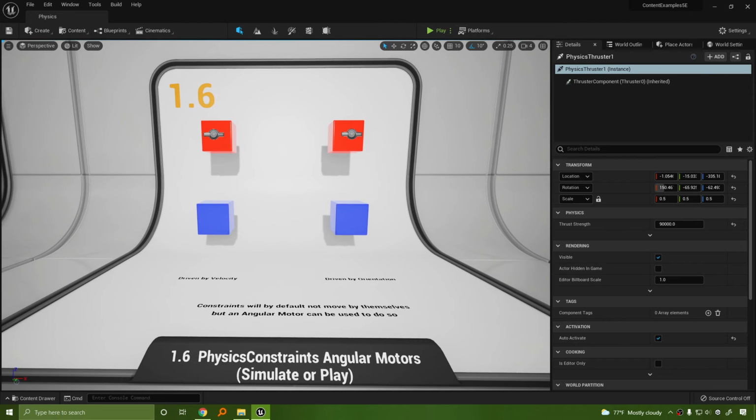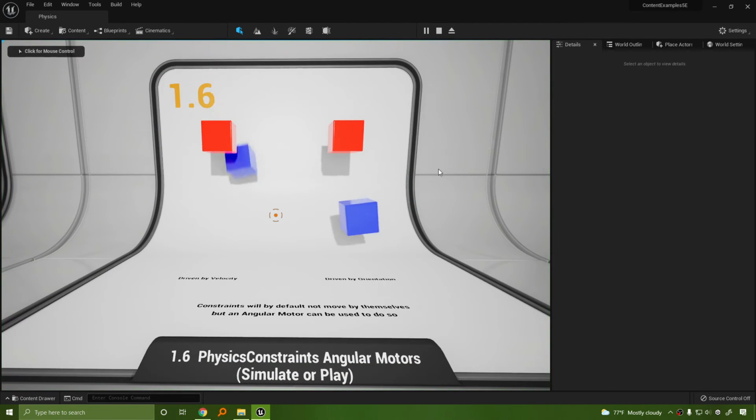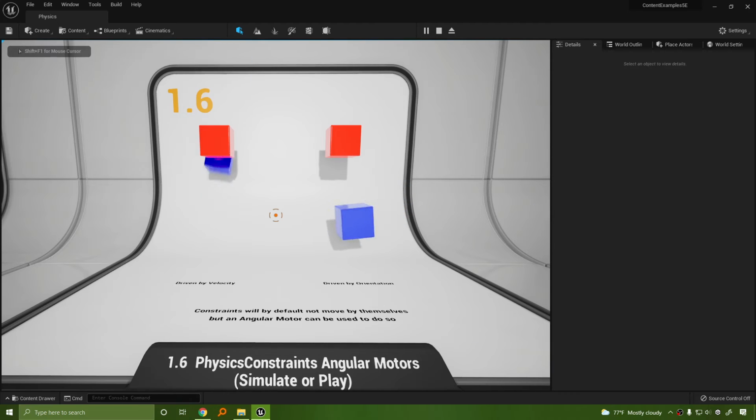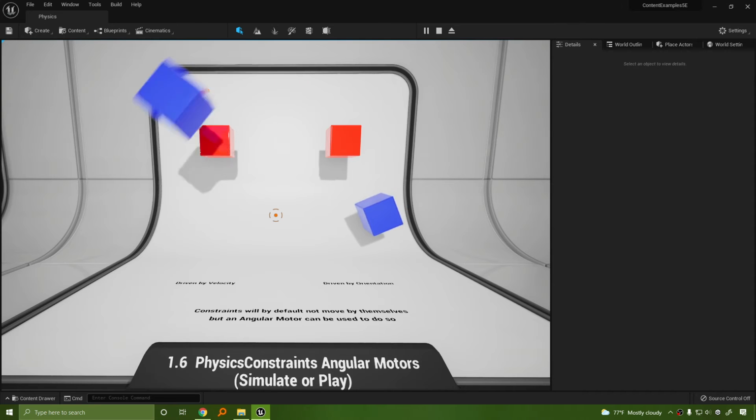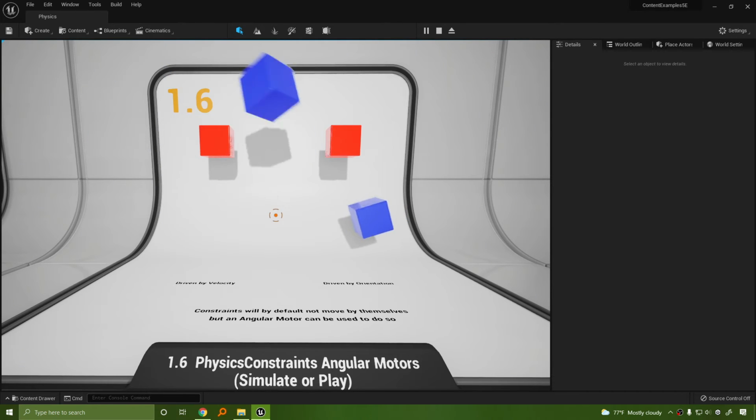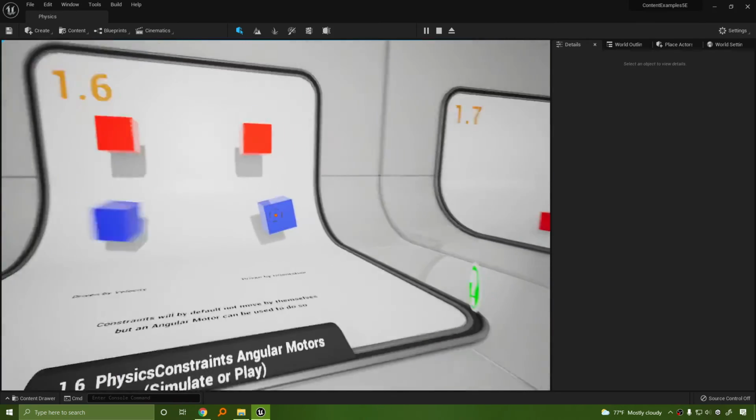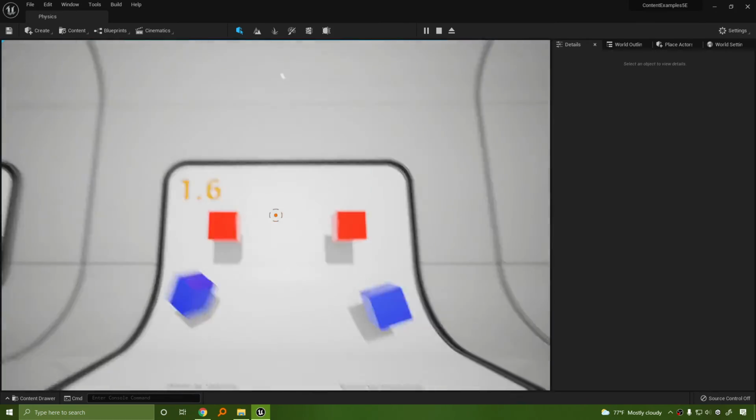I'm going to just go ahead and play immediately. Alright. So this is what's referred to as an angular motor. In physics, any physics with an angular motor will spin. But the detail is, how is it going to spin? Angular motors are driven by velocity, right? Angular motors driven by velocity apply constant force and they spin, whereas position-driven, like the one on the right, will attempt to obtain an angle based on the size of the spring and the dampening applied to the spring. This is more like a natural spring, and this is more like...